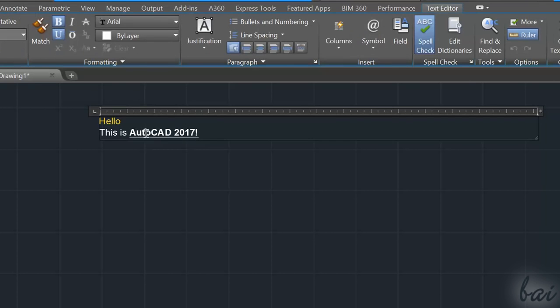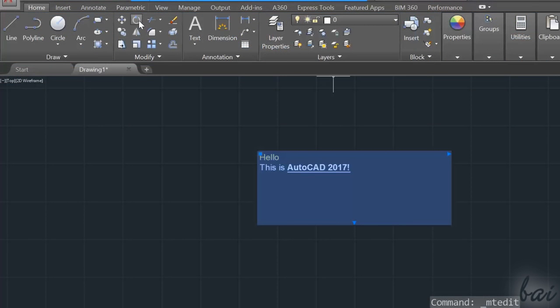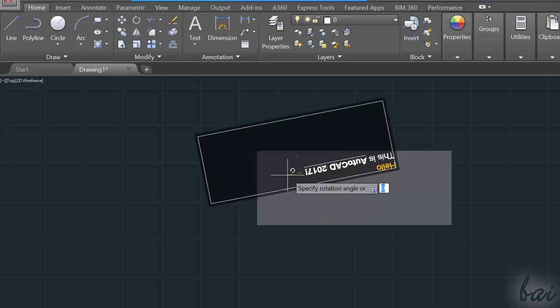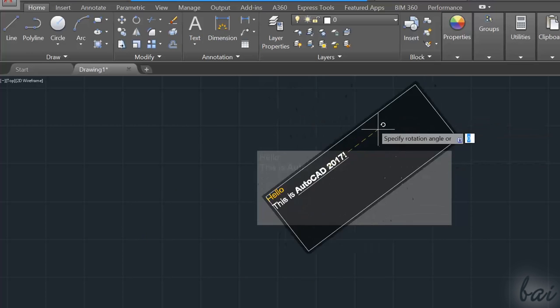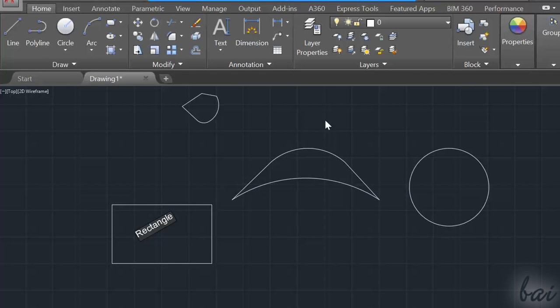Double-click inside to adjust the text content. Due to the text area, this object can be edited just like 2D objects with the modify tools just seen. In case you need to leave short text annotations on your project, you can simply use the quicker single-line tool. This does not use any text area.